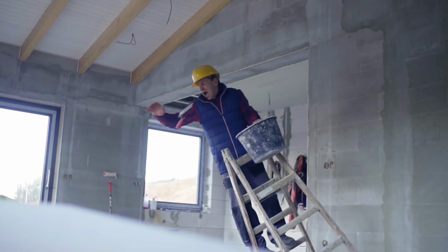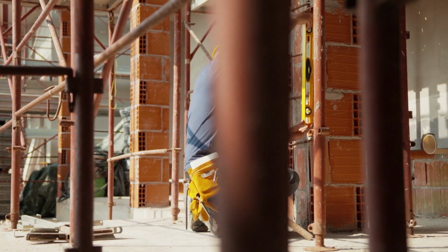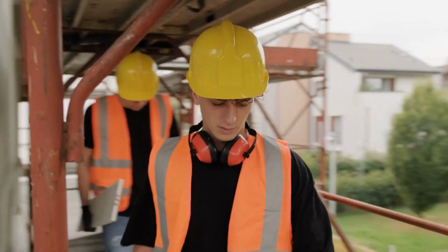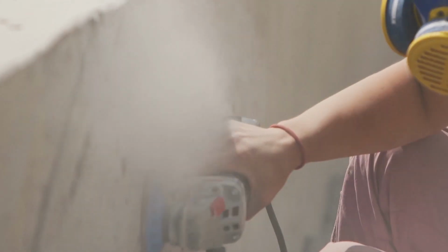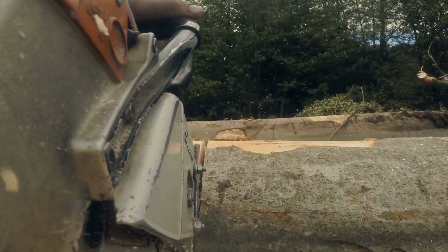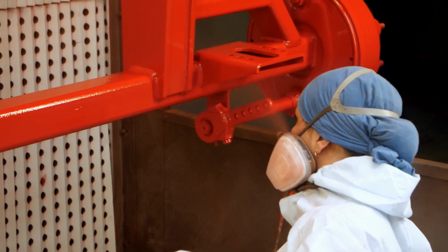It takes into account things like the types of hazards, where they're located, and how much of a risk they pose to employees. For example, they might identify dangers like falling construction materials or tools, which signal the need for hard hats. Or they might anticipate airborne dust from cutting concrete or wood chips from sawing operations, which would call for safety glasses or respirators.